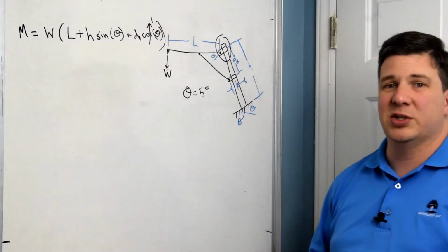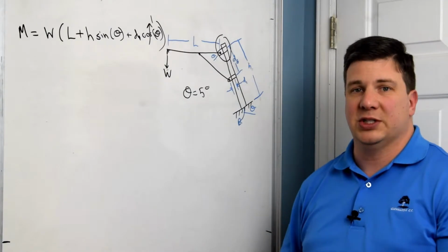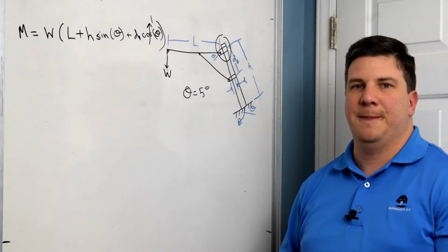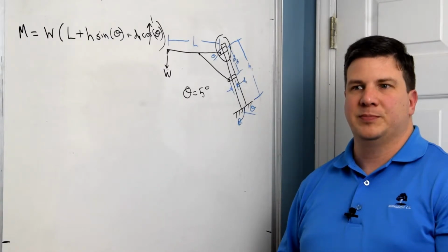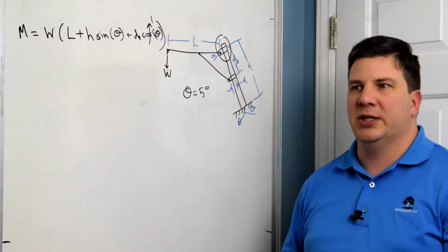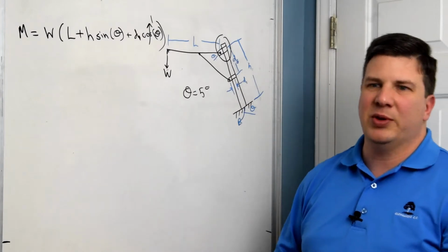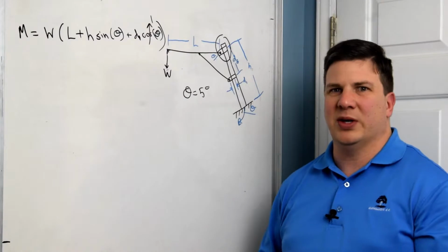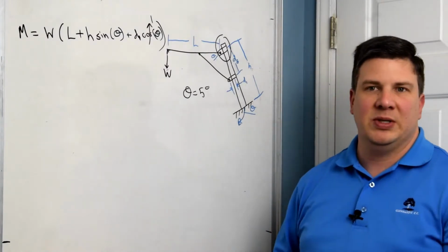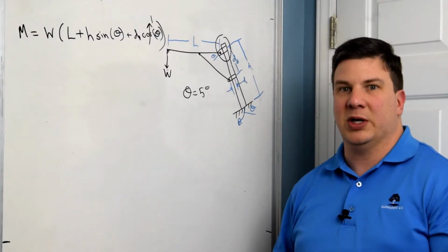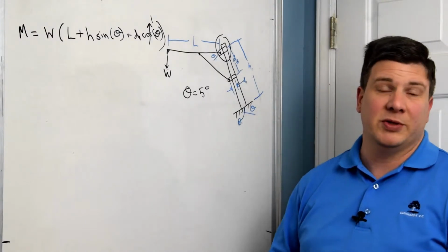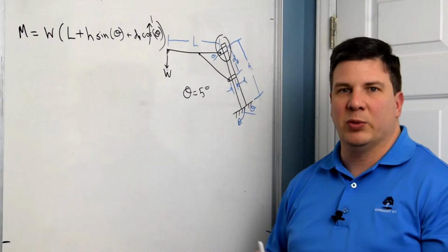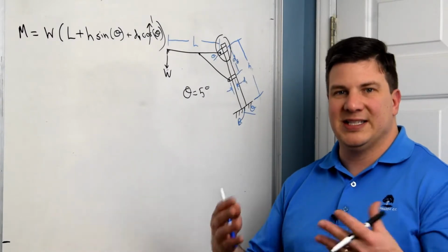The first thing we're going to assume is our coefficient of friction, and it's going to be something high. Steel on steel is generally about 0.3. If we oil the steel, it can go down to, I think, as low as 0.1. Obviously, we're not going to want to oil it. We probably don't want a coefficient of friction that low, because we don't want this thing moving around wherever we want it. Move it, and it stays.